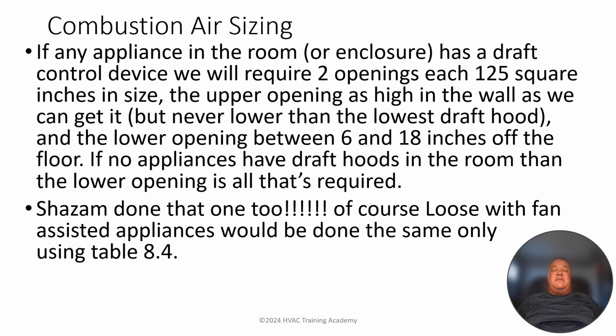If no appliances have draft hoods in the room, then the lower opening is the only one that's required. As soon as we have any draft hoods, as I mentioned, 2 openings, both the same size. So really, that's it. We're done with that one too. Of course, fan assisted would be done the exact same way, only using a different table.